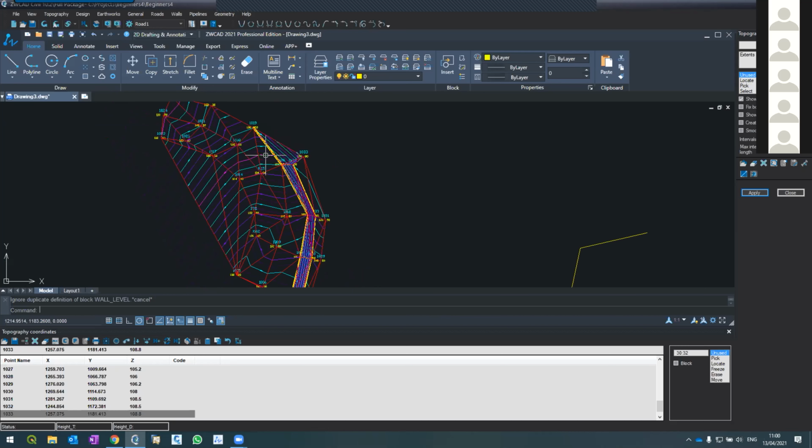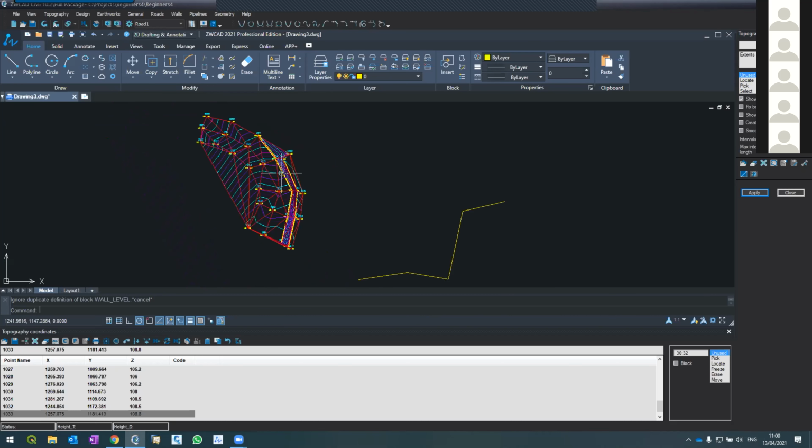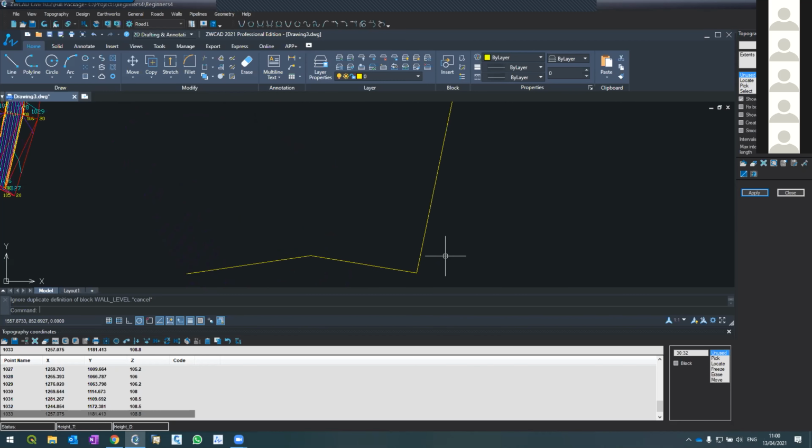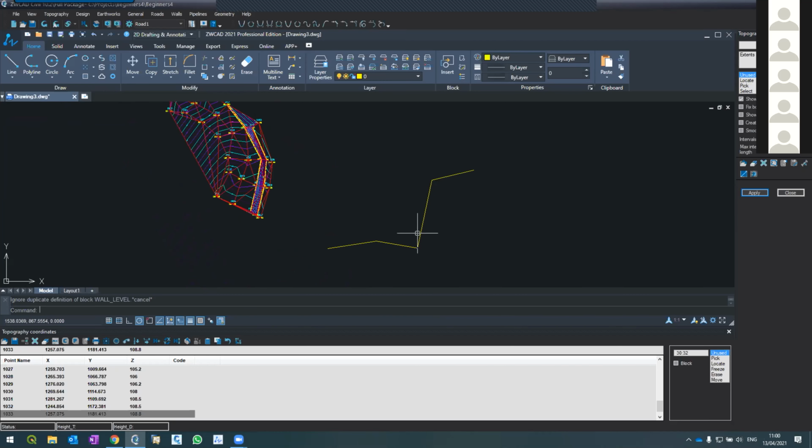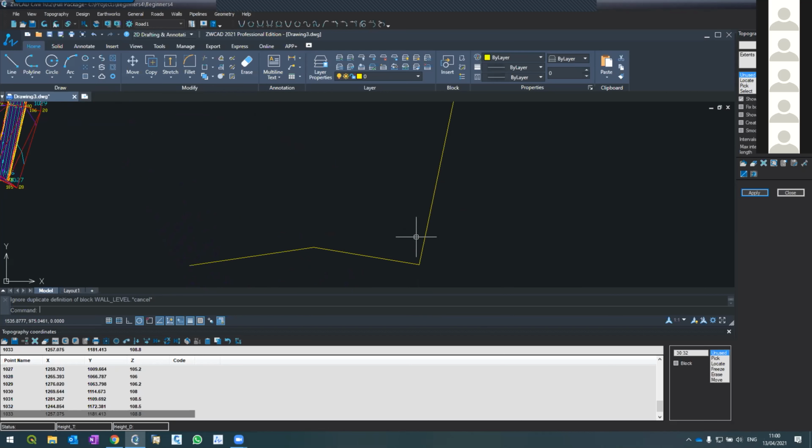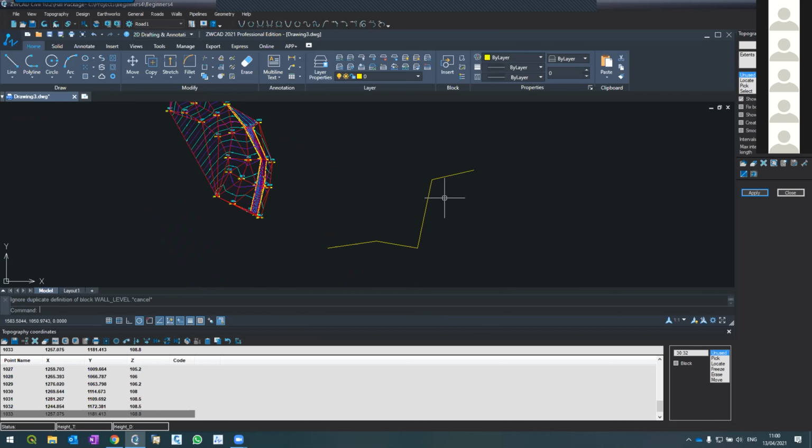In practice, in the field, we create breaklines. Since we don't know when to interpolate or not, we create breaklines when we have gaps or sharp changes. I'll give you an example. This cliff, but it can also be in something that all of you know. Let's say this is the road.